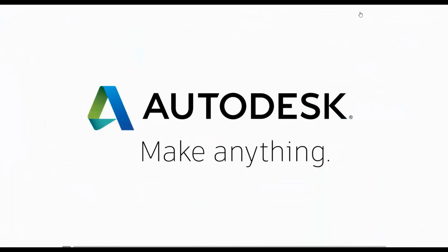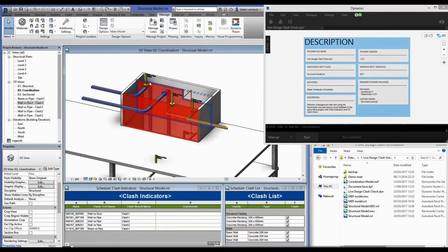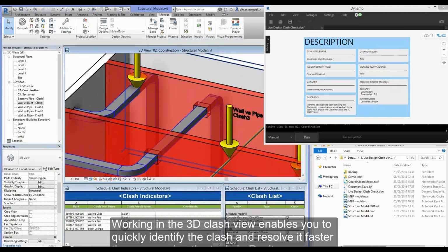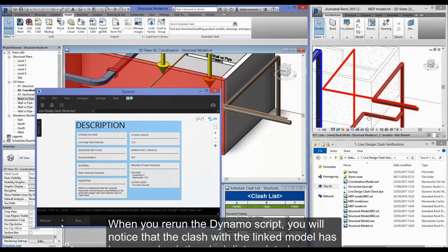Okay. Right, I know that was very quick, but just to give you an indication there, having the ability to see those clashes inside of your Revit model and actually fix it and add in penetrations immediately is a huge advantage, right? Traditionally, you'd have to go back and forth between the models or use your switch back command to see where those issues are, right? But the script reduces that workflow magnificently, right?